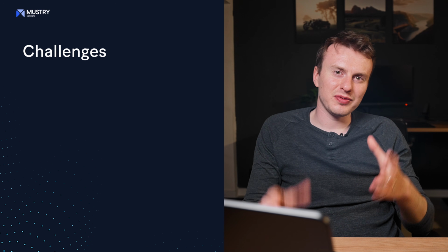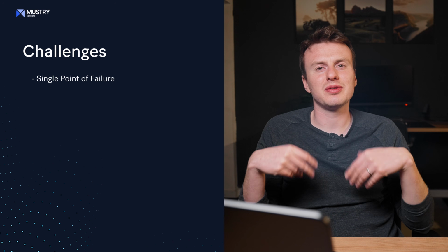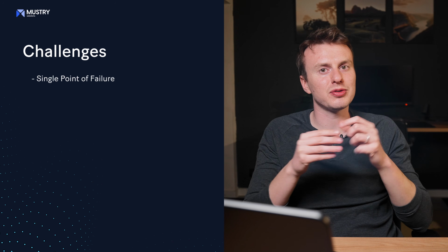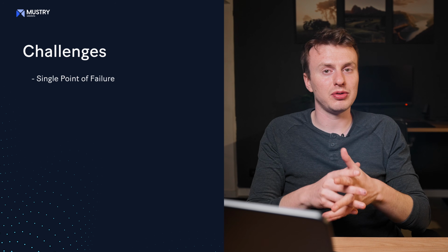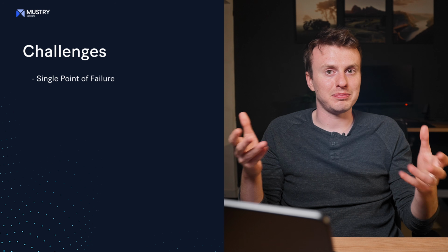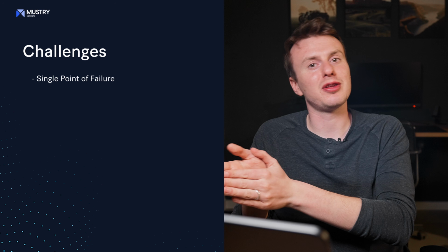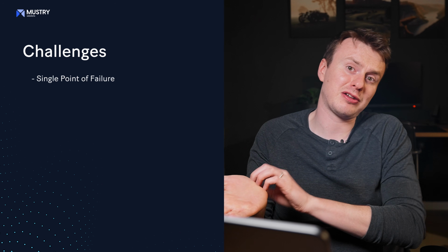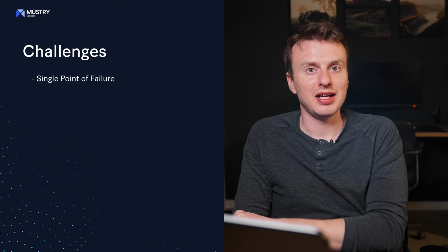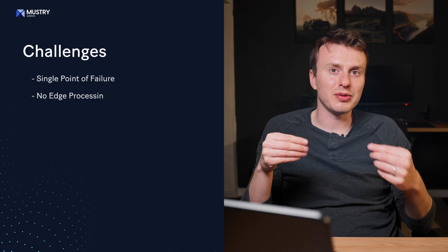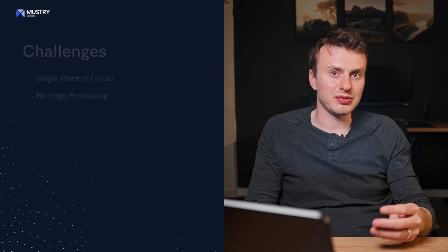What is the challenge of using a single Ignition? Well, the first one is a single point of failure. Just because you don't have your edge devices, you also don't have logic that is happening at the edge, so you won't have a backup strategy there. Unless, of course, you use Ignition's redundancy strategy, which actually solves a lot of that, and always make sure you have a backup. The second challenge is because you don't have edge processing, you might hit your limitations sooner.